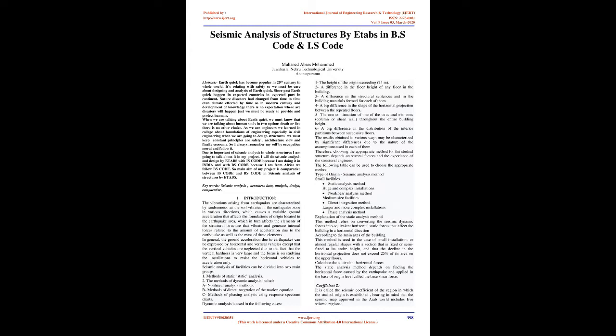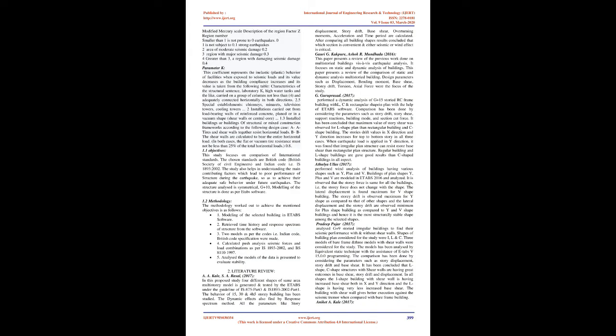In general, the ground acceleration due to earthquakes can be expressed by horizontal and vertical components, except that the vertical components are neglected because the vertical stiffness is very large, and the focus is on studying the structures to resist the horizontal components of acceleration only. Seismic analysis of facilities can be divided into two main groups.